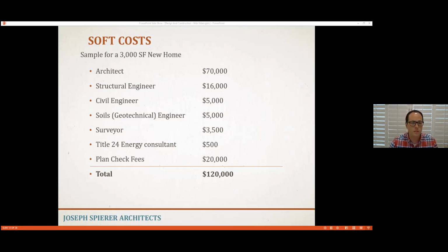And then you have a civil engineer. They're an important piece of this puzzle too, because they help create the site drainage. They help drain the site away from the building so that you don't get water infiltration, which I know you guys see a lot during inspection. That all boils down to bad civil engineering. If the civil engineering was done properly, there wouldn't be any real chance for water to come into the home, because the site would have been drained properly.